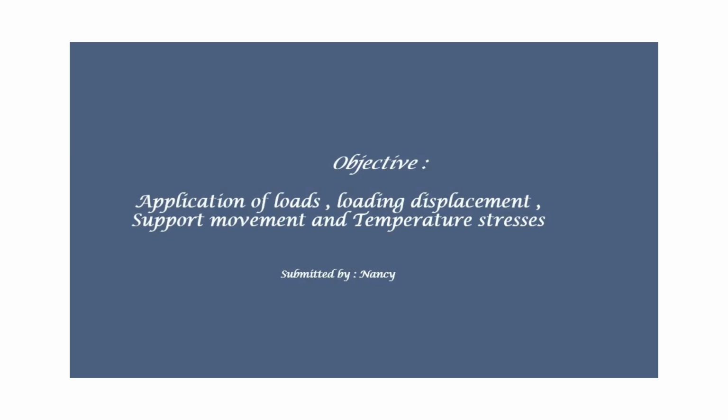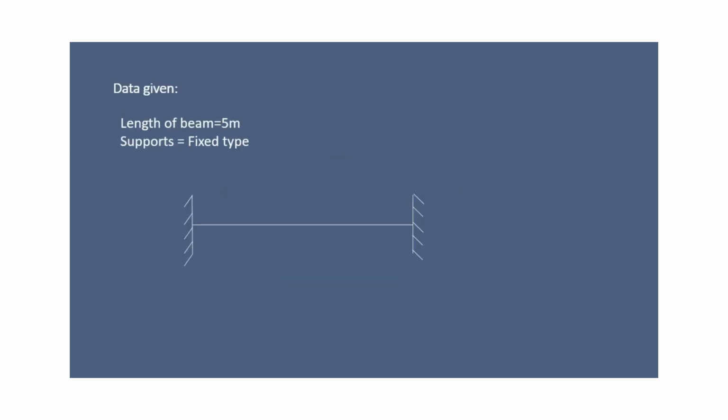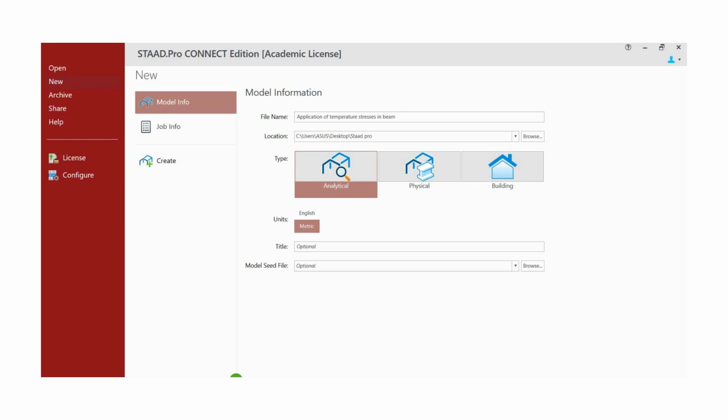Hello everyone, in this video I am going to describe the application of loads, loading displacement, support movements and temperature stresses. For that, here is the data given, that is a fixed beam having a length of 5 meter. So for that, click on new in STAAD and then fill the file name and click on create.